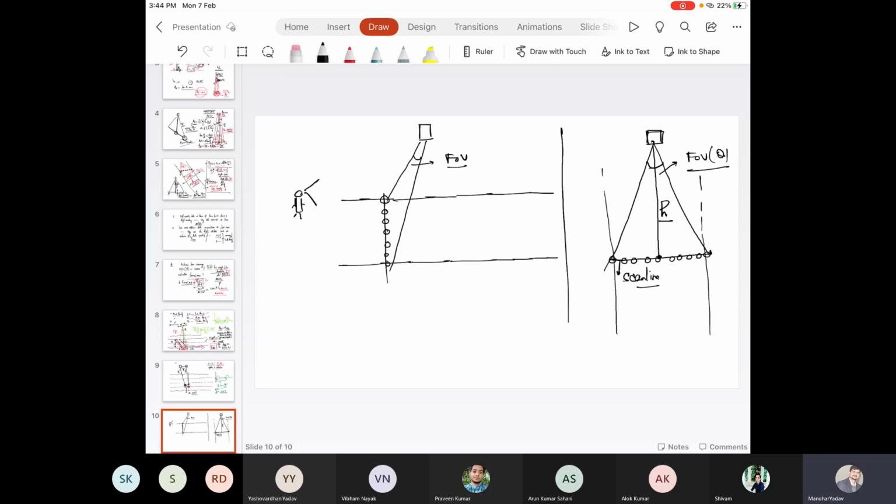And two other parameters are defined with respect to the sensor system itself. The first is the pulse firing rate: in 1 second, how many laser pulses are fired by this sensor system? The second frequency is the scan frequency. Scan frequency means how many rotations are made by the mirror in 1 second.